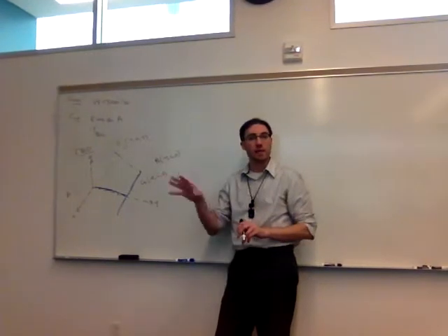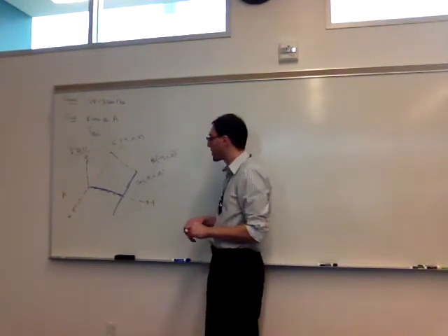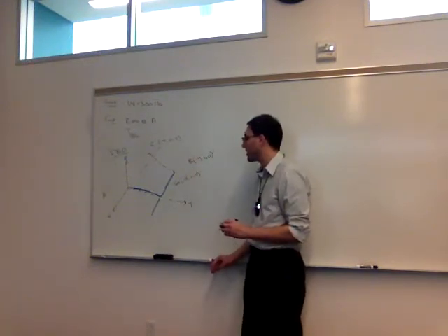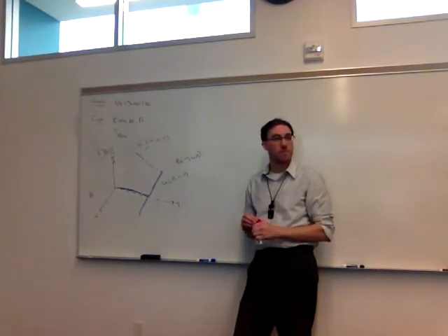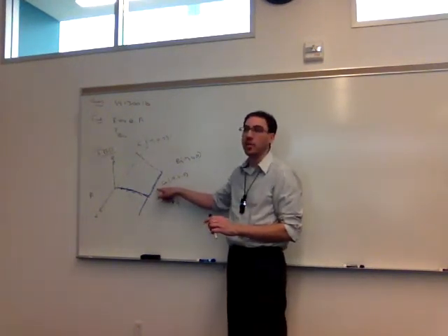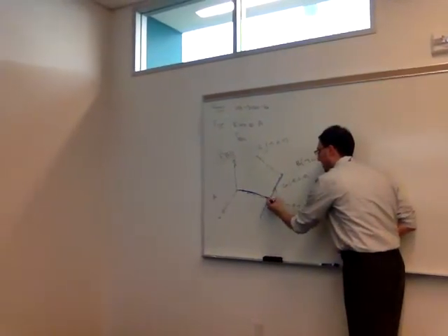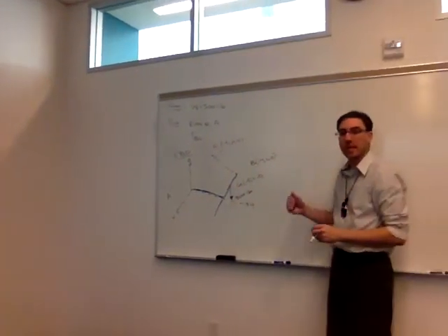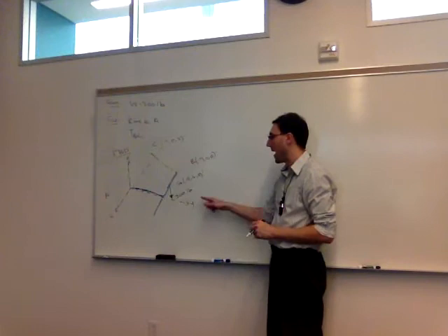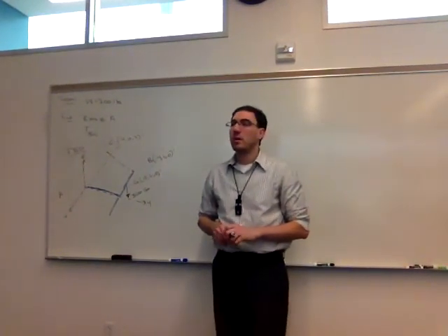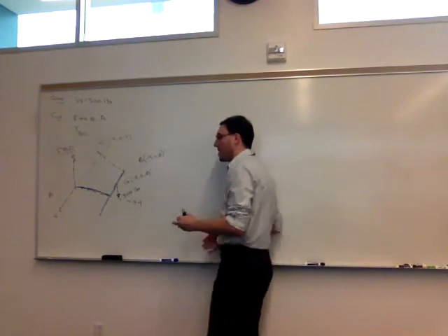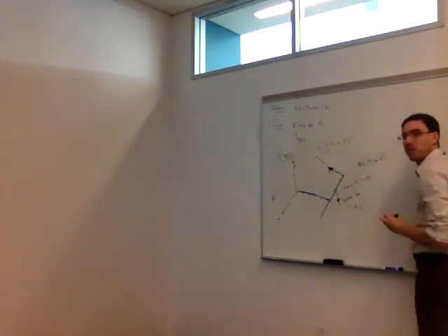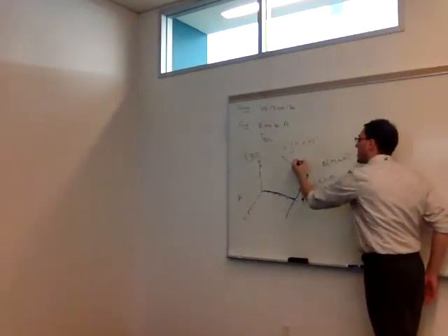So now we have to start adding the forces that act on it and the couples that act on it. I usually, just out of habit, start with the external or the applied forces. So what applied forces are acting on the beam here? Right, so that weight that's hanging off of it at G, so that's acting in the -z direction. It'll have a value of 300 pounds, which will be in the -k once we get to the equations. But it's in the -z direction acting at G. Right, so we have another force. It has to be a tension, so it has to be pulling at point B. And we know that it's pointing towards point C. So that's the tension. I'll call it TBC.